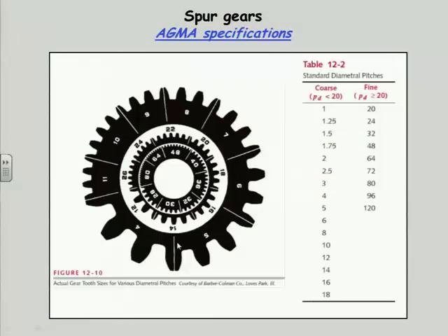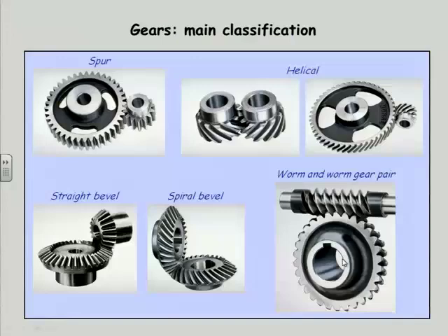This shows the relative sizes, not an absolute scale, of the various diametral pitches. And again, small numbers are big teeth and vice versa. So they typically run from 4 to 1. This shows 4 as the largest. But here are the standard numbers of diametral pitch that you can buy from a gear manufacturer in the United States. The metrics will be totally different because they're reciprocal, they're in millimeters, and you can't run metric gears in mesh with US gears and vice versa. The principles are the same, but the standards are different.